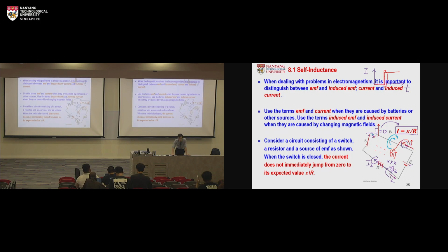That is to say, when I1 increases, at the same time there will be an induced current inside the same circuit which tries to suppress I1. As a result, when you close the switch, the current will gradually increase instead of sharply increasing.